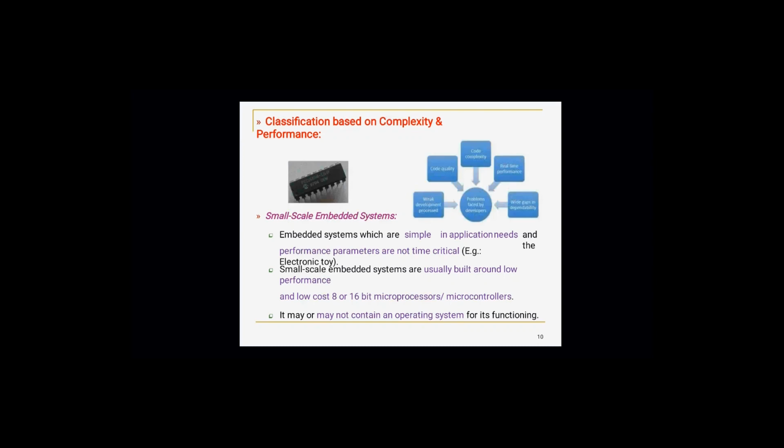The processor we use, even if it is ARM or any other processor, basically an embedded system processor is called a microcontroller, not a microprocessor. Earlier we only had microcontrollers inside embedded systems. Now we have microprocessors, because ARM is neither a processor nor a controller. It is in between. So let us merge everything and call it a processor itself. A small scale embedded system will have a processor with very little capability. So a calling bell, electronic toys, even a music player in your car is a small scale embedded system.